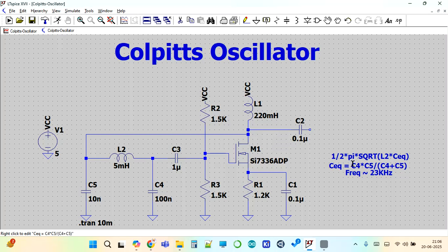But in practice, such small capacitors or inductors cannot be achieved in discrete values. Correct? So this is where, in RF circuits, these are achieved using MMIC circuits, where based on the topology you can achieve the particular frequencies by having those MMIC circuits etched onto whatever substrate you have.